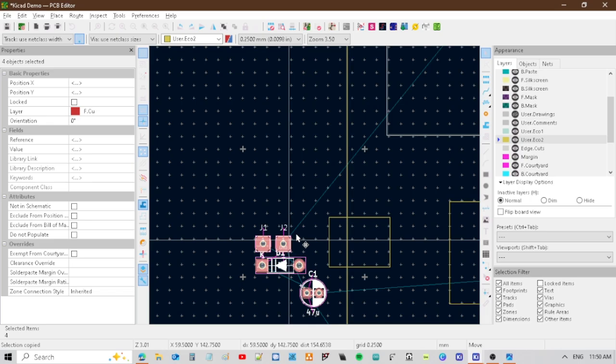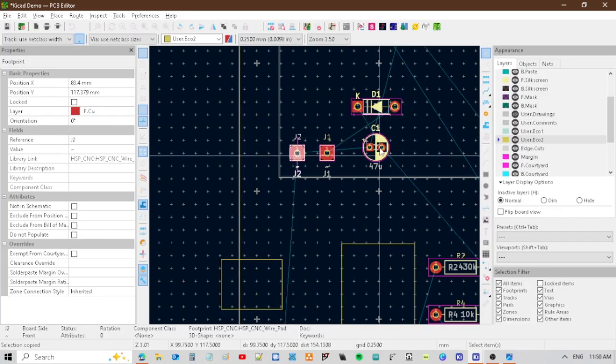We're going to put our power connector on the right and our ground connector on the left, because then I can add this diode. Anything you're picking, it will highlight it on the schematics. If you don't know what a component is, click on it, highlight it, flip over, it'll show you where it is in the schematic. So Alt-Tab is something I use a lot when I'm doing this.